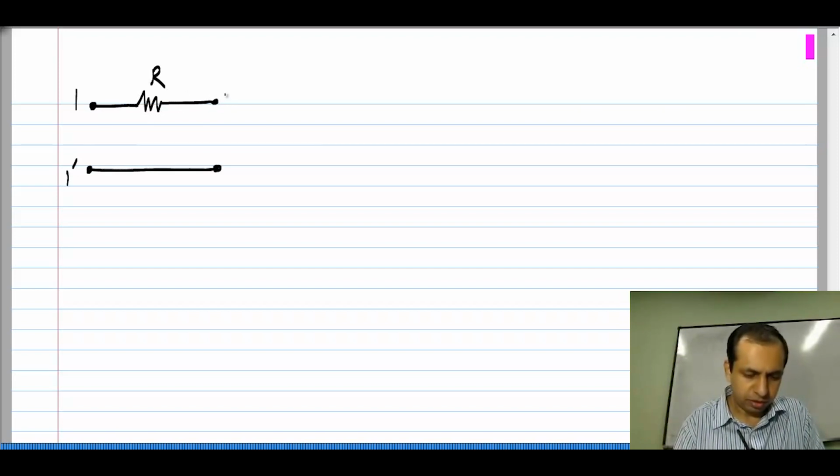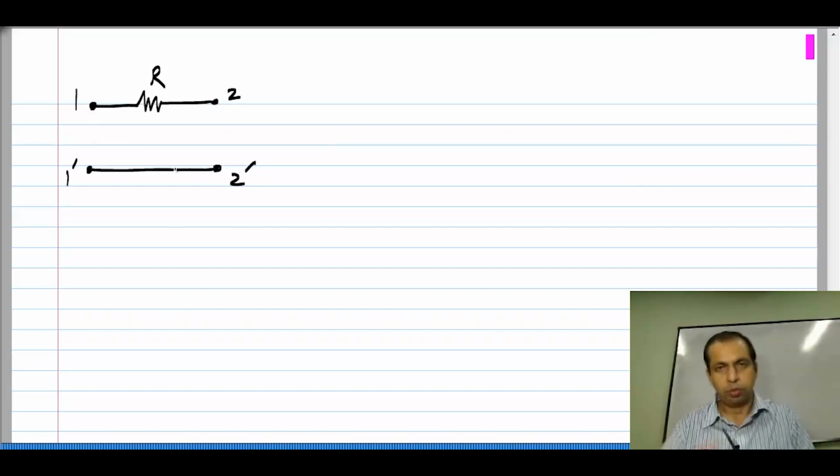So, let us take a very simple circuit. Just this. This is the 2 port and it contains a single resistance. Now, please go ahead and calculate all 4 parameter sets for this, that is Y parameters, Z parameters, G and H parameters.